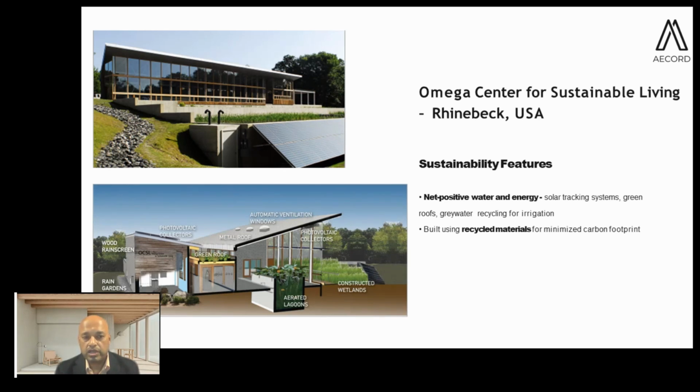What is the reduced embodied energy of the material, how much recycled content and how much recyclability is there, and what happens to the material after the life cycle. So it's a holistic approach of complete life cycle analysis, from extraction of the material till the end of the life cycle of the building, and that material goes back to recycling or landfill, whatever it is.